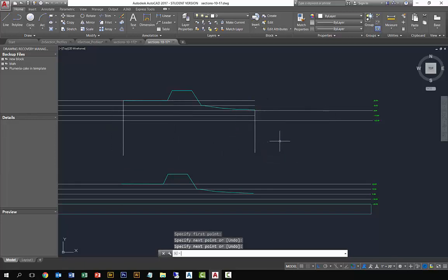and another line. And now I'm going to check the distance to make sure it is 264. So I'm going to use dist, D-I-S-T, snap, 264 feet. Perfect. So everything came in at the right scale. So now I need to scale it down to model size.